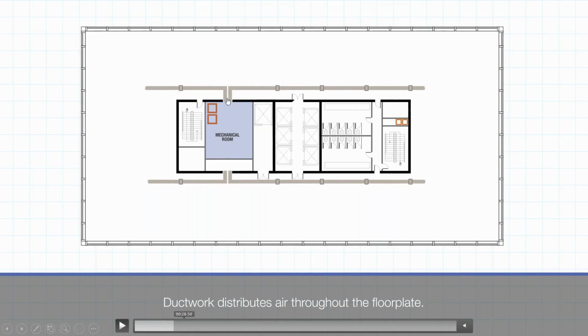Now, with a multi-story underfloor air system, your return air path is on the bottom side surface of the supply plenum on the floor just above, so you do get thermal decay. And so there is some heat transfer up into that supply plenum. You don't want the air to travel that far, from 60 degrees from the mechanical room out several hundred feet to the perimeter space. So if you have a design like this, you will want a little bit of ductwork to essentially get the coolest air to within about 50 feet of the perimeter space.